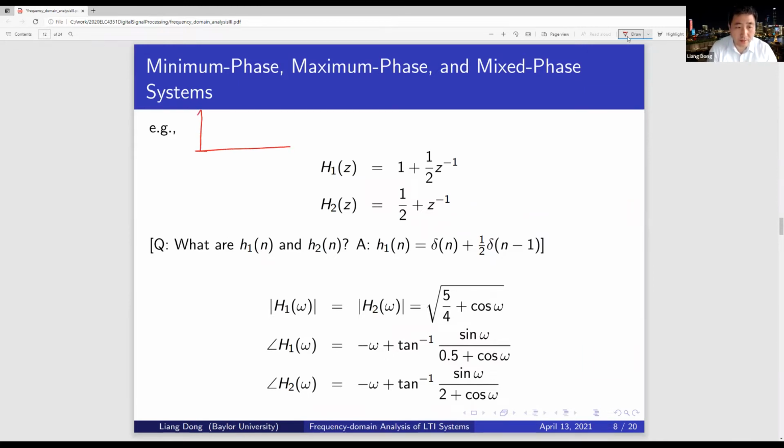When I plot this image, we have the H absolute value. So for a low pass filter, it goes like this, from 0 to pi. But there is also another element we are not looking at carefully, which is the phase, the angle of H omega. We mentioned a linear phase, right?